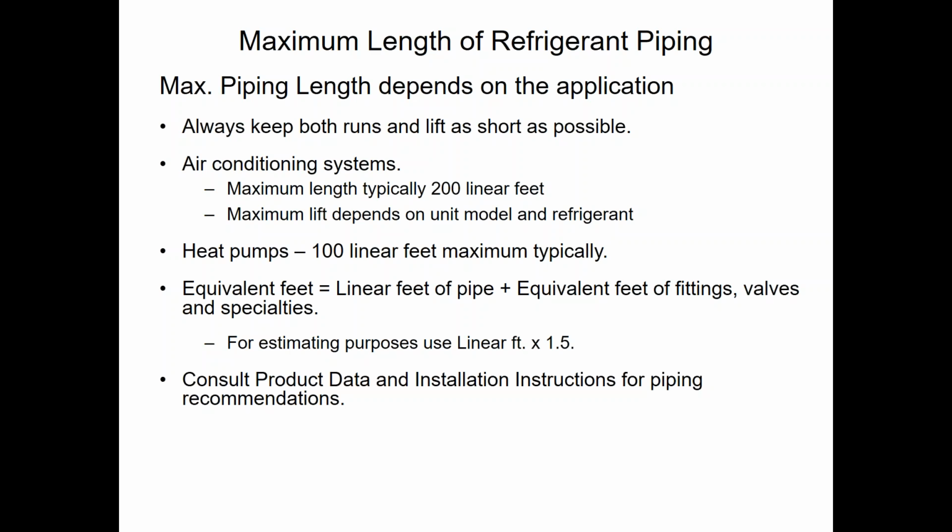Just make sure when you're looking at the charts that you're understanding that you're in the linear length or the equivalent length. Okay. And most of the charts, pipe sizing charts, are in the installation instructions. With some products, we also have it in the product data. Always make sure you're in the most recent product data or the most recent installation instruction when consulting or going to the piping charts.